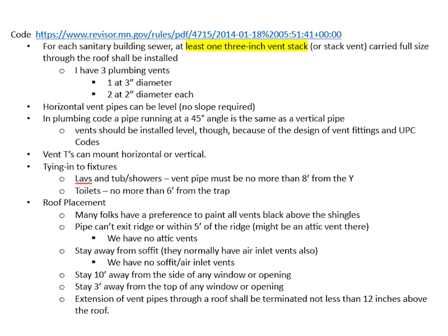Stay 10 feet away from the side of any window or opening. Stay 3 feet away from the top of any window or opening. Extension of vent pipes through a roof shall be terminated not less than 12 inches above the roof.